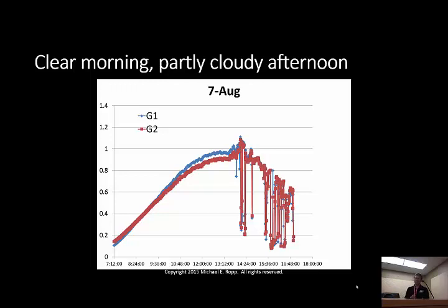I have to toss out a couple of caveats here. You can see that the ramp rates on the irradiance are pretty extreme. But remember, this is a pyranometer. It's 1 square centimeter, so it's a relatively small device. If I spread this over a PV array of relatively large extent, that is going to moderate the ramp rates somewhat. But you can see the depths of some of these cloud passages. The shadows are dark.